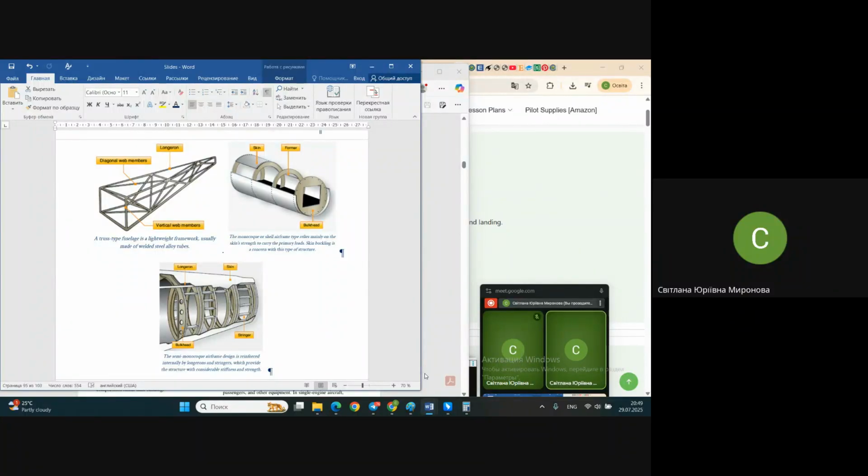Or no, that is not always true. First airplanes were flying with low speed, and they had rather low specific loads over the surface of their structures. And in this case, more weight effective were these truss-like structures, practically made of sticks.